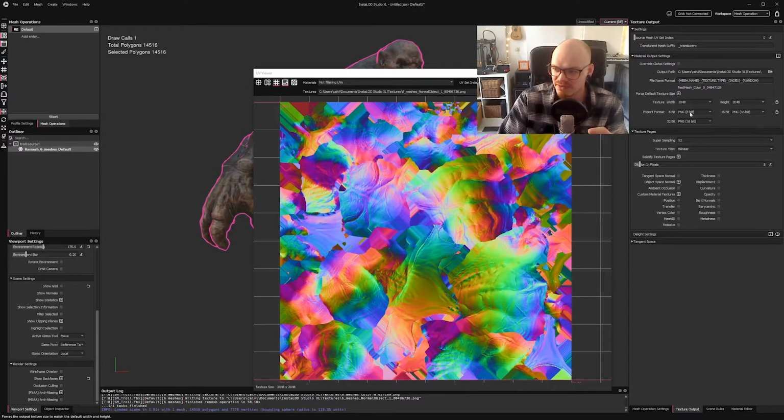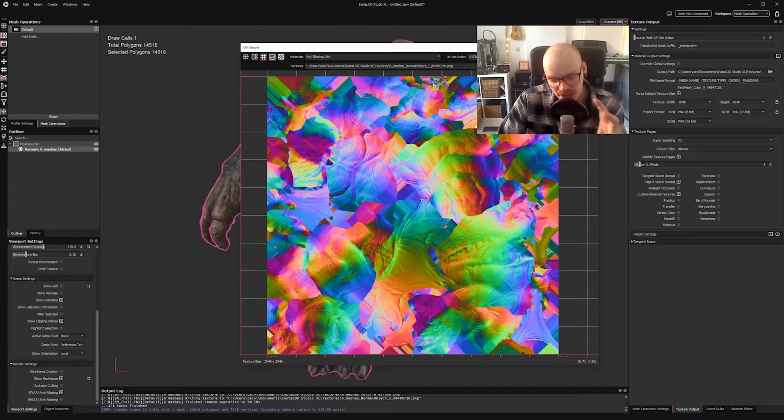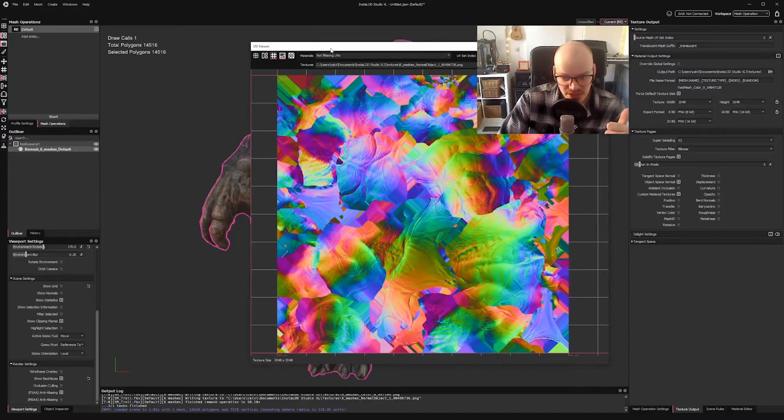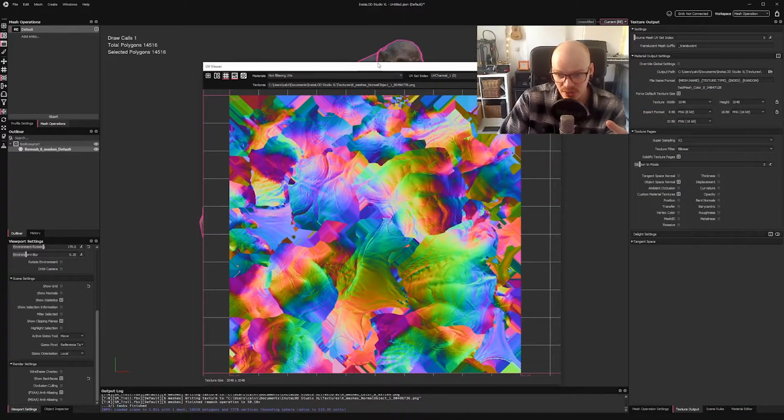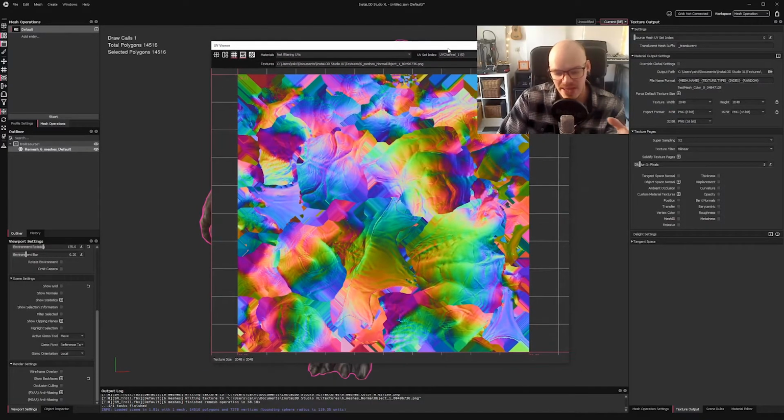Okay, so just in case you haven't seen the bake settings, we've got those up here, the texture size, and that's, I believe, the only thing that you couldn't see that I was talking about. Anyway, the 3 textures we've baked are the color texture, then the normal map for the silhouette, which is the object space normal map here, for the geometry, the silhouette, and so on. And then the third texture, which we've baked here, is actually coming from the input character. The input model had its own tangent space normal map. And that's how we ended up with 5 textures altogether as an input.